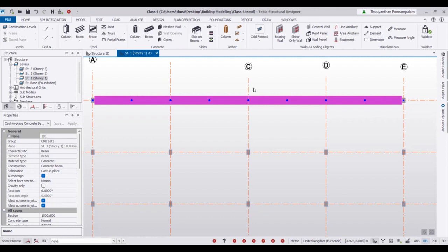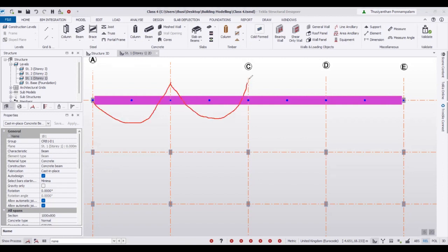So that means the expected bending moment diagram, I am expecting this way. So this one is 0 moment. This is the center of the beam, right? I start from here at 0, and it goes here hogging moment, then comes to sagging, hogging here, sagging. But actually here it can be like this.